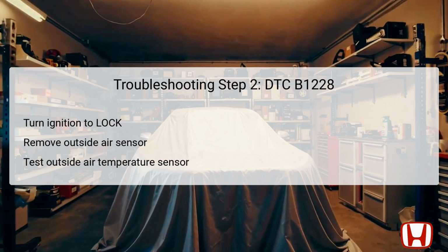In the second step, start by turning the ignition switch to the lock position. After doing this, carefully remove the outside air temperature sensor to allow for a proper inspection and testing process. The sensor must be tested to determine whether it is functioning correctly. If the outside air temperature sensor is found to be okay, you can proceed to the next troubleshooting step.